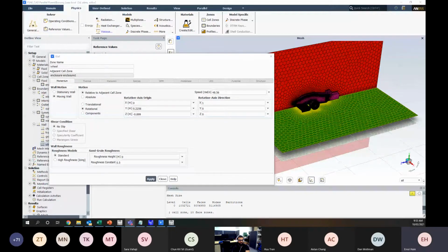For a 3D cold flow case, does symmetry and zero wall shear stress boundary conditions on the enclosure provide the same result? For most conditions, symmetry and zero wall shear will provide us the same result. But once again, go into the help file, get the actual mathematical specifications to ascertain that before you use it in whatever project you're doing.